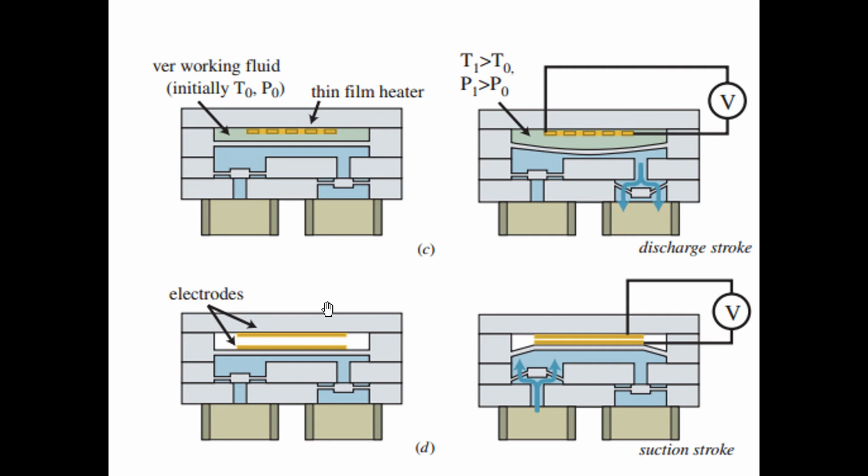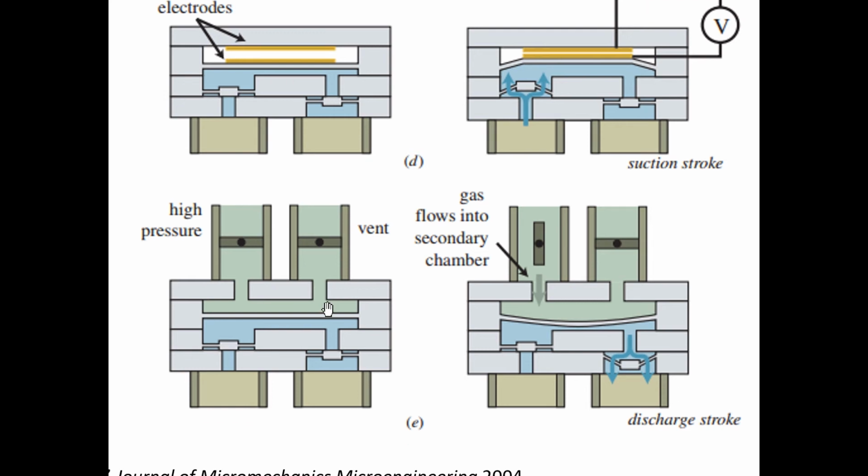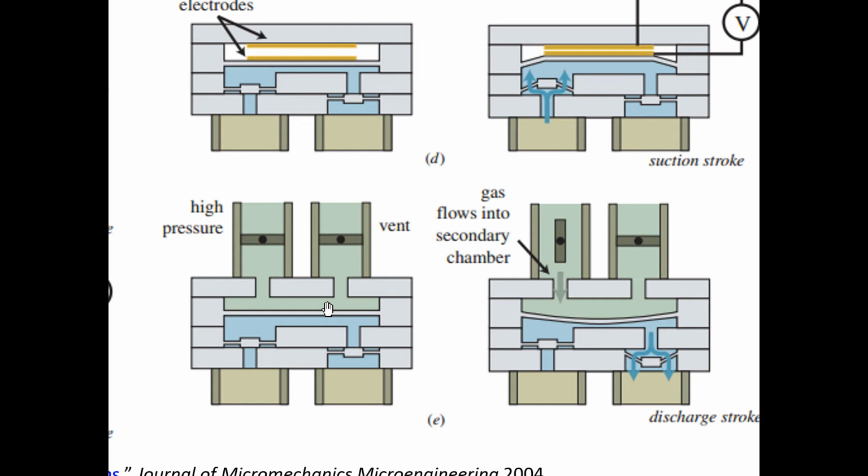Whereas a chip like this, you can make just out of this PDMS, a plastic or elastomer. Adding metals and piezoelectrics into the device increases the cost of the device quite rapidly, to the point where it's not disposable anymore. So one of the reasons these designs are popular is because all the expensive stuff is off of your chip.